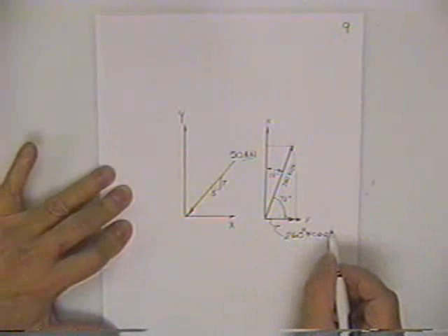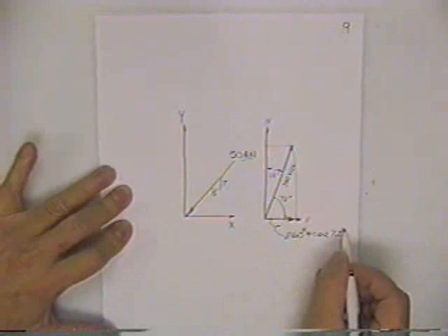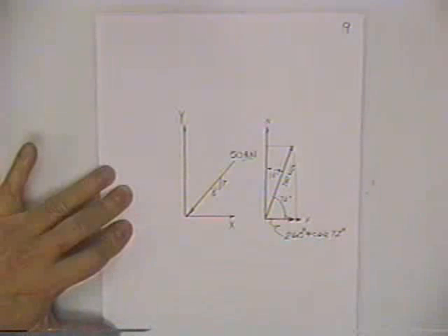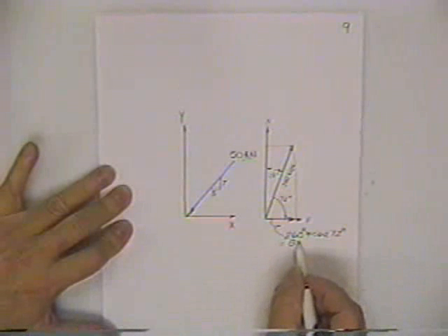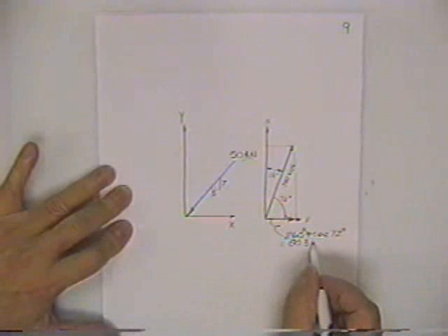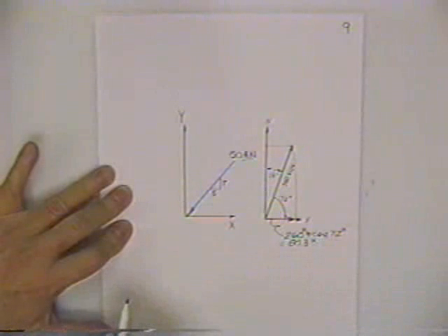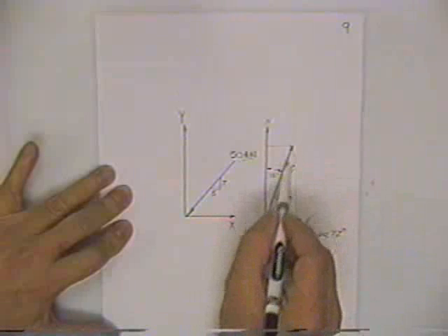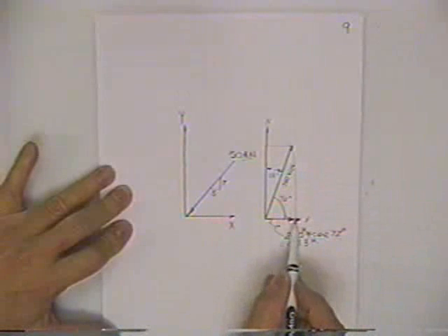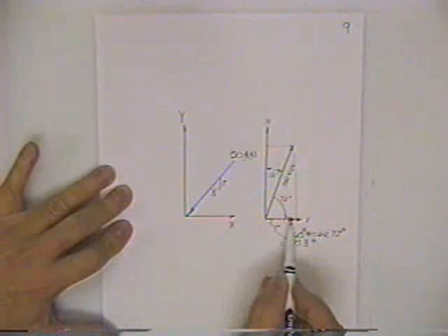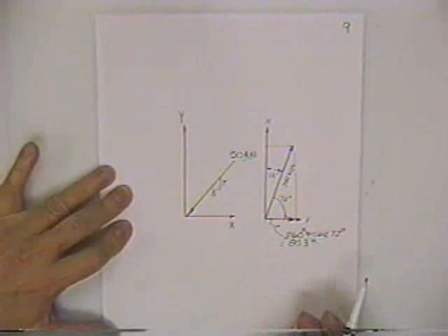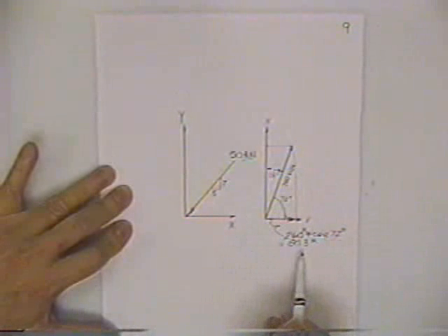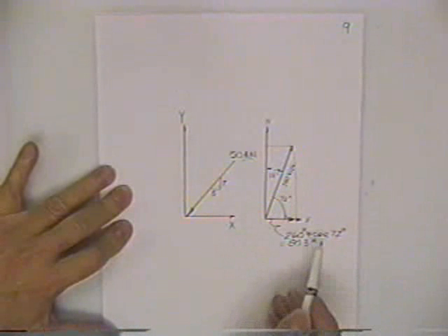Then 260 kips times the cosine of 72 degrees. I've got a friend of mine here with me running a calculator and the camera, so 80.3. Now you should be able to tell if it is reasonably accurate, because if this thing is about 260 inches long, then indeed this side of this triangle is about 80 inches long. So 260 kips, about 80 kips is probably correct.